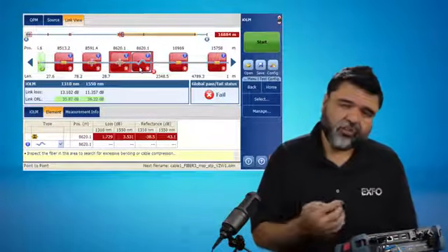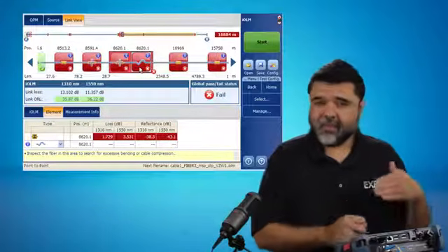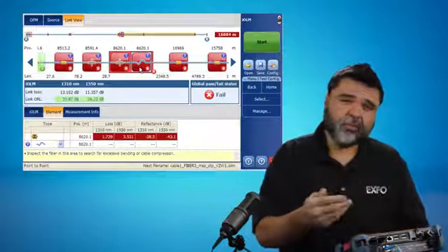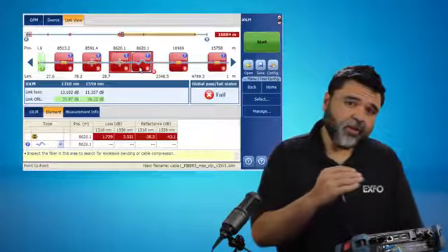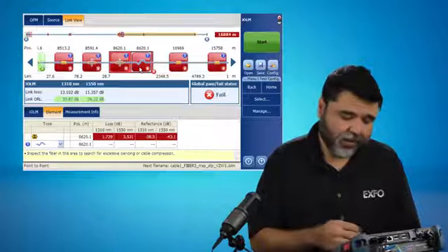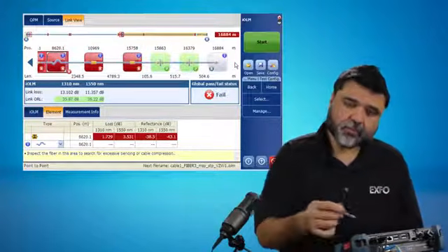And so this is more than a simple linear trace view. We have a linear trace view with our OTDR that takes the event table and applies a linear trace view that's block diagrams based on that one single shot. What this does is it does a comparison over multiple traces, multiple acquisitions, and it gives you the most comprehensive view of a fiber that you can get.